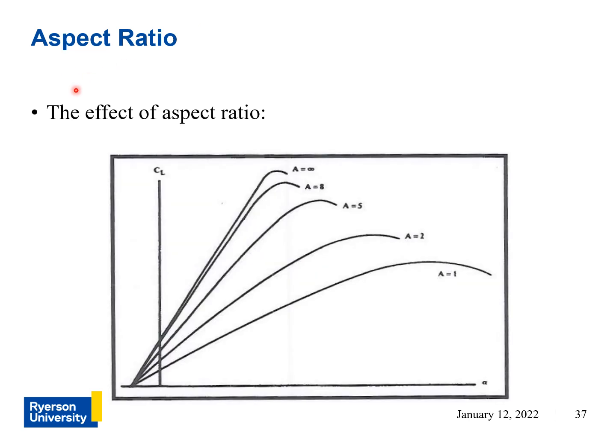So again, a wing with a high aspect ratio has tips further apart than a wing with an equal area with a low aspect ratio. So that means that the amount of the wing affected by the tip vortex is less for the high aspect ratio wing than for a low aspect ratio wing. That translates to the strength of the tip vortex being reduced for the high aspect ratio wing.